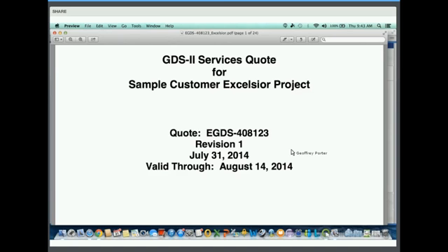Yeah, I think we're talking about the same thing. A postscript to that is what the person means is how well you fill the mask with die, and changing the aspect ratio sometimes gets you more die per mask. Yeah, so they know what they're talking about. That's what we're shooting for as well. That's mask field utilization. Yeah, and when we're in an automated situation like we are now, we can do that right away.